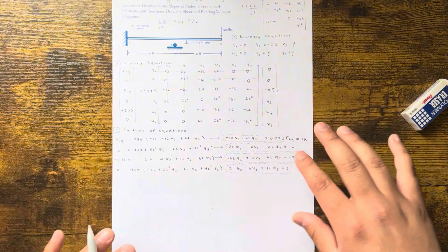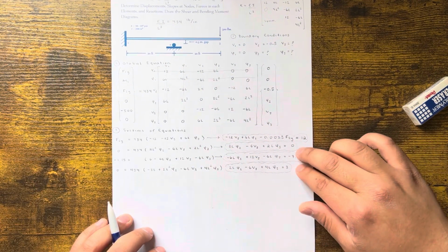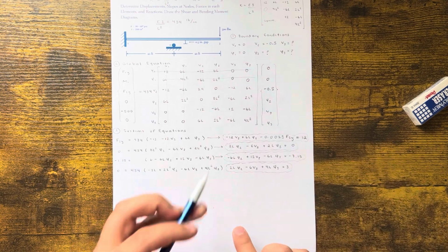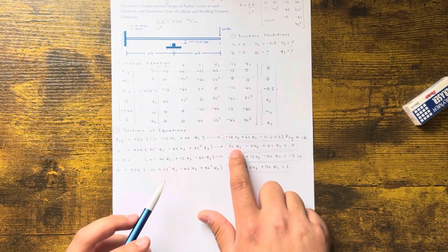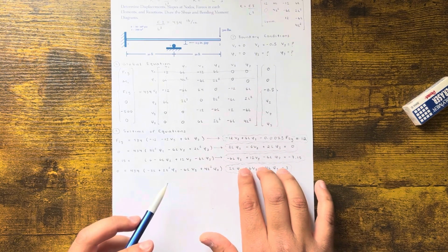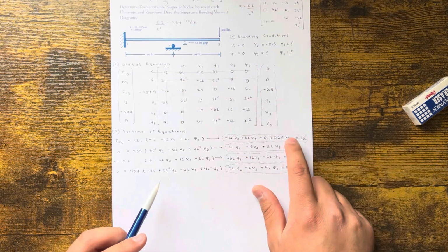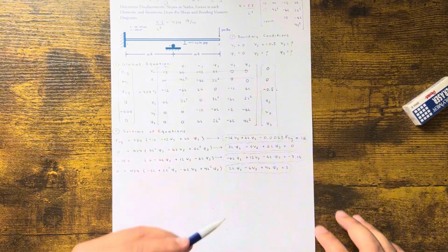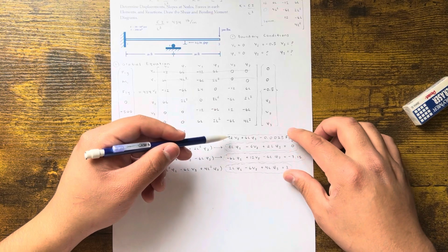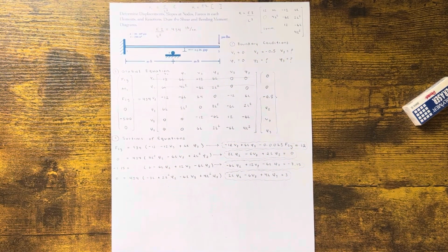And look, before I go into that part, this one's the only one with F2Y. So this is 3 equations, 3 unknowns right here. Just forget the first equation. You could solve 3 equations, 3 unknowns, get those 3 numbers, and plug them into here: V3, Phi3. In this case, there's no Phi2. And then you'll find F2Y, okay? So you could do a 3x3 if you want, or just do the whole 4x4. They'll give you the same answers, and that's kind of what I did here.